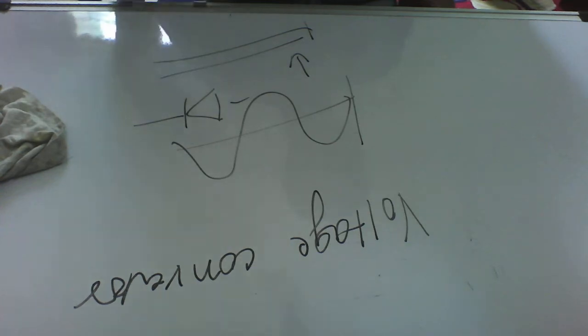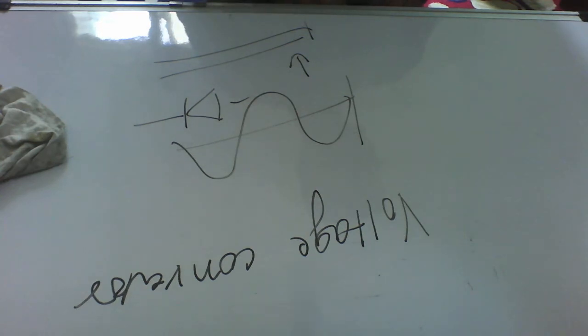For lower voltages, Schottky diodes are used as rectifiers with fast recovery time. For even lower voltages, MOSFETs are used as a synchronous rectifier. The rectified output is smoothened by a filter with inductor and capacitor. To get a perfect output without any AC component in it, capacitors and inductors are used.